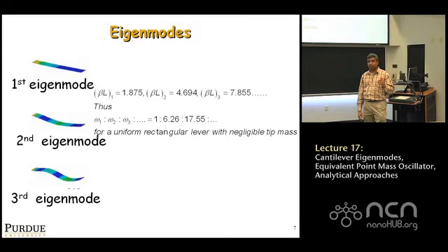So what you clearly see here is that these frequencies do not scale by 1 to 2 to 3 in beams. They do not behave like strings. So in other words, they're not harmonics. And in other words, they're not good for musical instruments. Musical instruments require harmonics. It's very important. That's why musical instruments tend to be more string or membrane-like structures which produce harmonics, whereas things that have bending stiffness are not so good for harmonics. They produce frequencies that are not harmonically related. Okay.